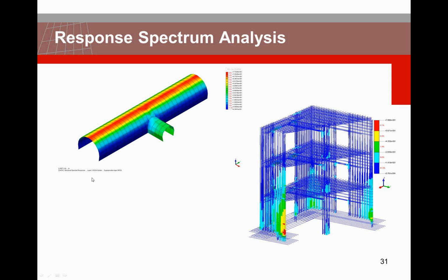This is the H result, probably not visible, but it means the high result. If you have no static load, your low result is just minus the high result. But if you have some static load, for instance the self-weight, then it will shift your band, and the high and the low will differ not only in sign but also in value.